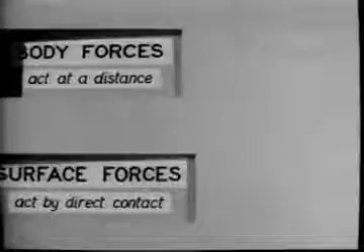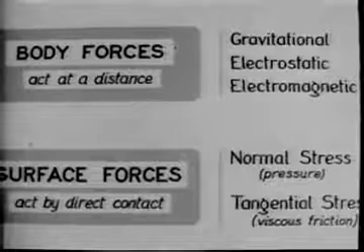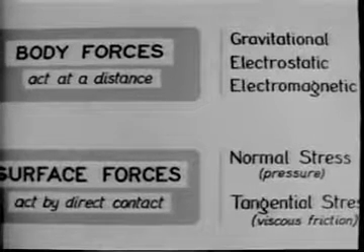Now we are ready to come back and think about how all the forces we have been discussing affect the motion of the fluid. First of all, it turns out that we need not consider gravity at all. In our experiments, the terminal speed experiments, the wind tunnel experiments, gravity in the fluid produced a buoyancy force which decreased the apparent weight of the objects.